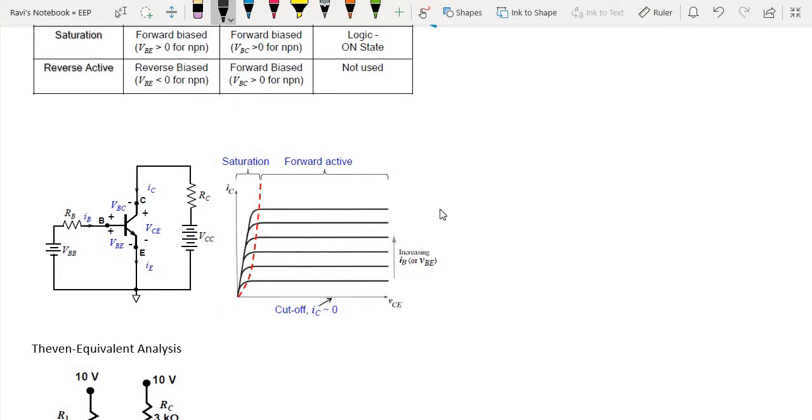For the amplification that we are focusing on, we look at the current that we provide at the input side, which is the base, and the current that we are able to extract at the emitter and the collector side. So the base is considered the input to the device, and the output is at the collector or emitter, where we have the amplified signal.